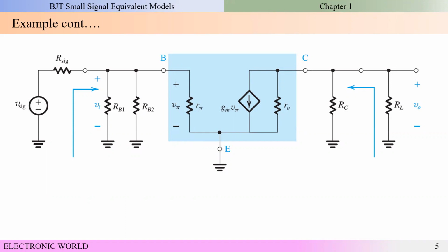So you might wonder what these arrows are. These arrows represent the input resistance. The input resistance is R5 with RB1 and RB2 in parallel. So you can see that this Rin resistance gives this kind of equation, and VI means the voltage of this terminal.